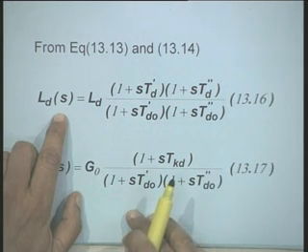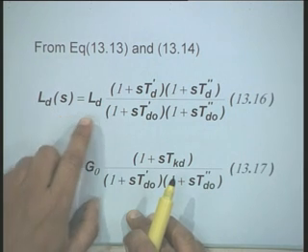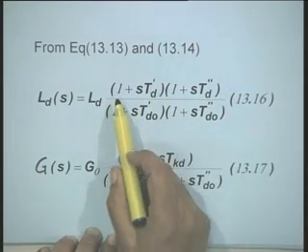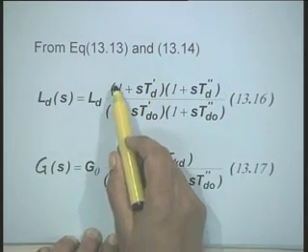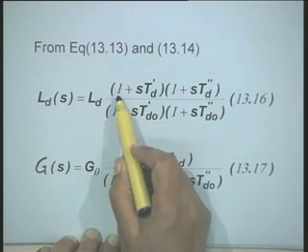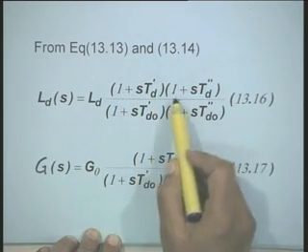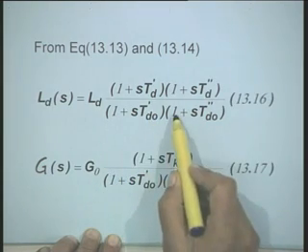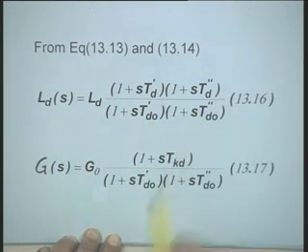These derivations can be carried out. Now, at this stage what is done is we write the expression for LDS, that is the operational direct axis inductance, as LD multiplied by the numerator, that is by this expression, which is having numerator as 1 plus S times T D prime into 1 plus S times T D double prime, over 1 plus S times T D O prime into 1 plus S times T D O double prime.